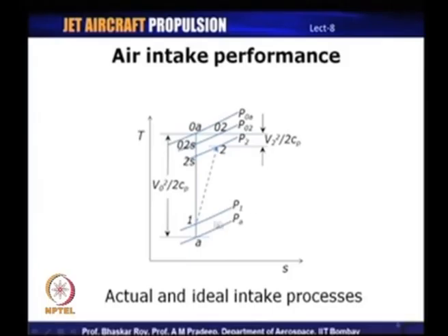So, this means that there is already some compression taking place, which is shown by the increase in static pressure here. But because this is outside the intake boundary, there are no losses associated with this process. The first compression process is known as the external compression, or pre-compression as it is denoted in some literature. Pre-compression does not suffer from any losses, because there are no solid surfaces which bound the free compression.